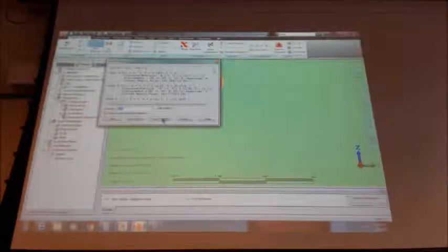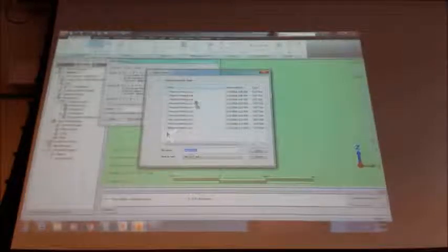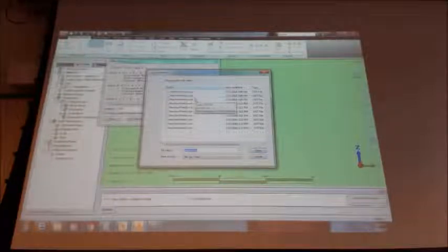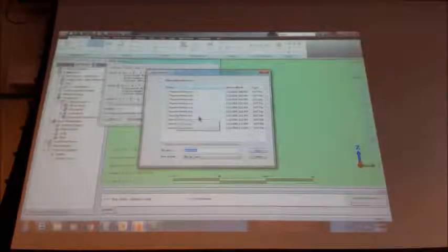So now you've got to do that for 5 holes and 2 directions. The way that I discovered to help facilitate that is if you save this to a report, and you can name it whatever you want. Just give it a name so you can tell the difference between your holes and maybe what direction you're going.